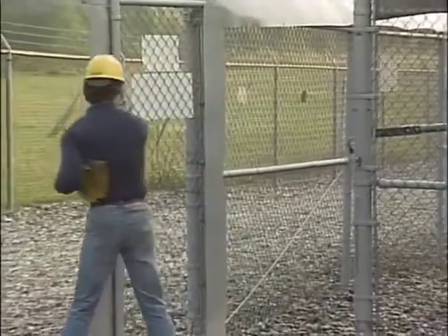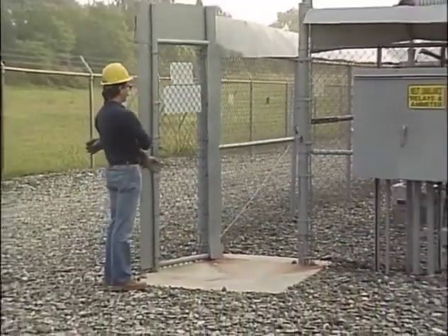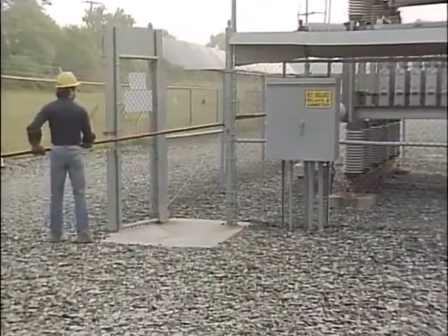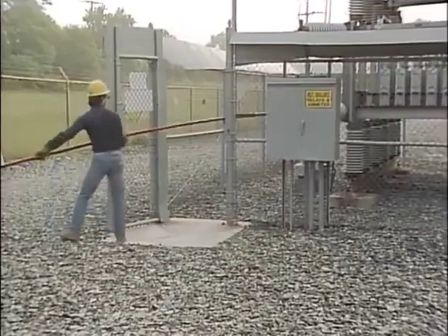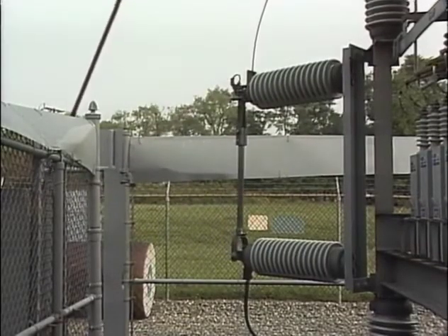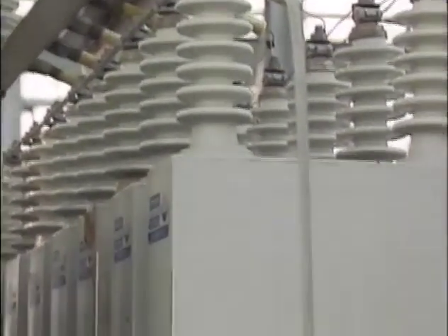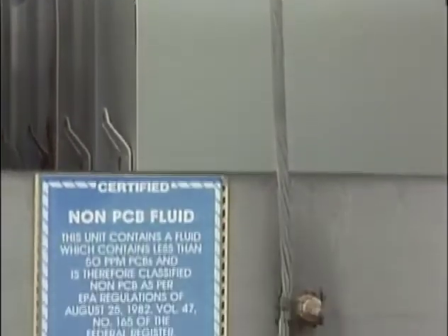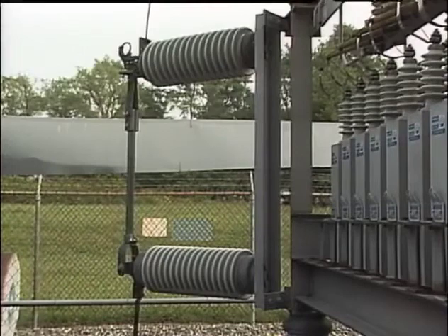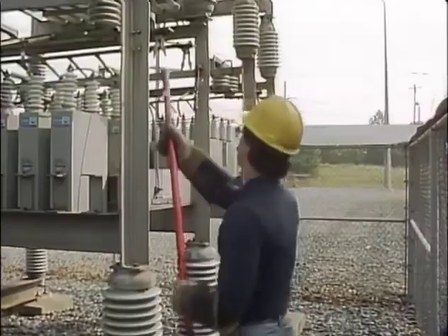As with any other capacitor bank, the 5 to 10 minute waiting rule should be observed before the bank is grounded. To ground this bank, the first switch that is closed is a master ground switch. Closing the master ground switch grounds the frame of the capacitor bank. The neutral terminal for each capacitor is connected to a conductor, which is connected to the frame of the capacitor bank. So grounding the frame effectively grounds the neutral of each capacitor in the bank.